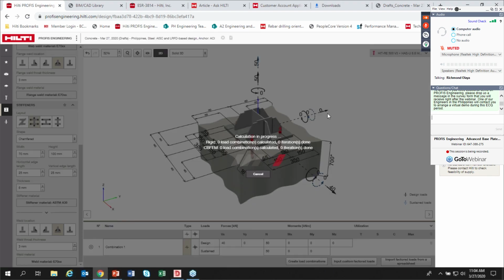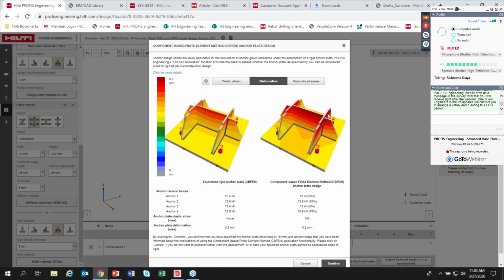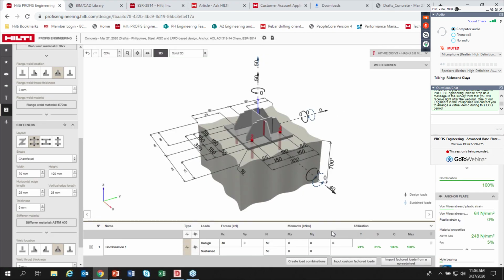Then calculate. The factor 0.55 was correlated from, I believe, ACI 355.4 for adhesive anchor test requirements. So it automatically checks for the sustained loadings throughout the service life of the anchor.